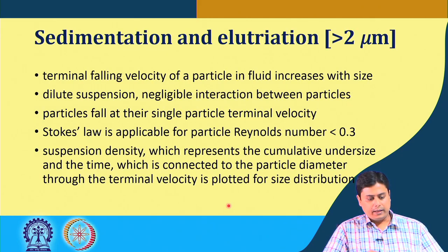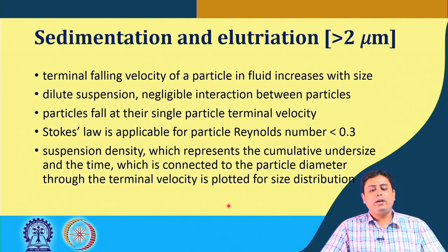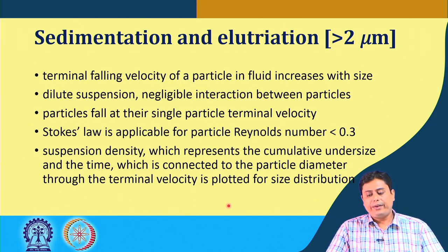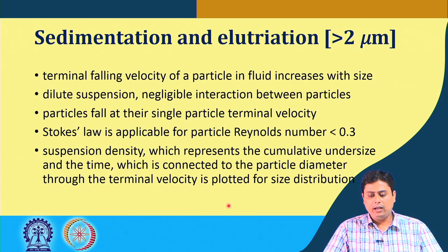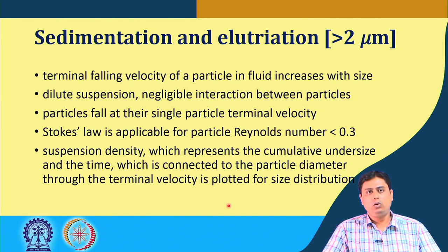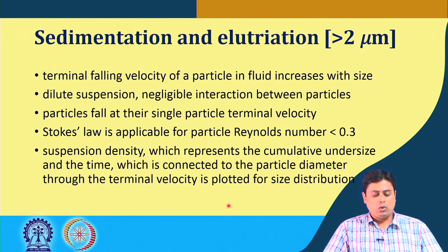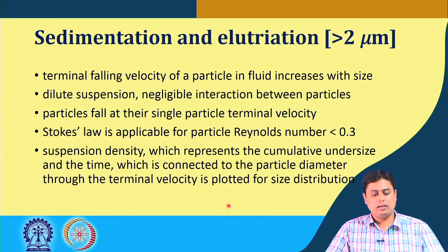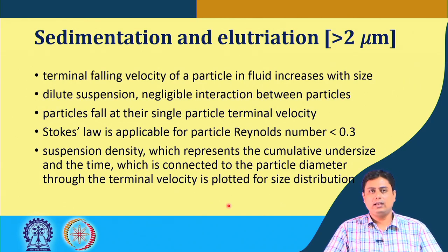The next technique I will discuss is sedimentation and elutriation, which helps us with particle size measurement for sizes typically greater than 2 micron. So, this technique is typically applied for particle sizes greater than 2 micron. Here the principle of the sedimentation process is based on the fact that the terminal falling velocity of a particle in a fluid increases with size.